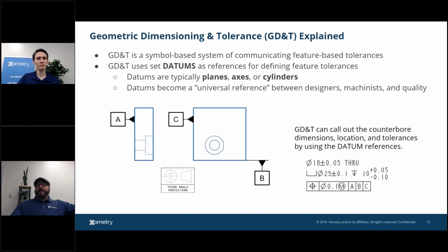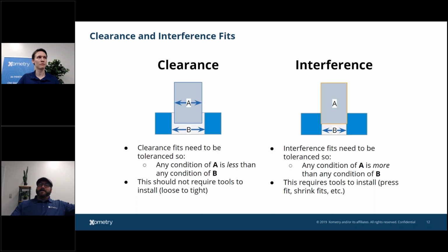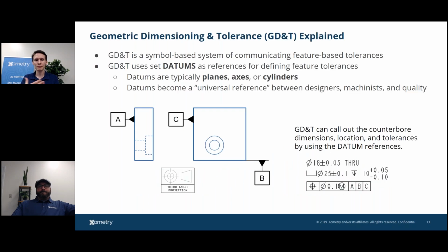And you'd be surprised, Greg, how many people design things to finish out size for size. Yep. So a 1/2 inch diameter hole with a 1/2 inch piece fitting into the inside is not going to work. Yeah, and I've even seen situations, so say you have metal and like metal, like aluminum, you could actually accidentally cold weld parts together with that, which is why you use different metals sometimes when you're looking at assemblies, especially pins to parts.